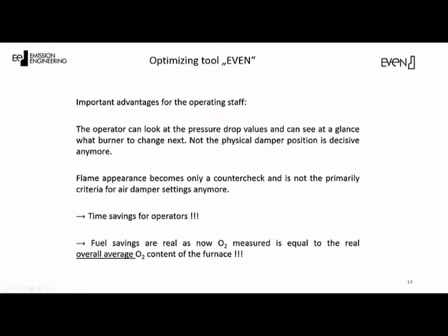Do you think this method is too time-consuming and complicated to understand? We assure you it's not. The measuring systems that we have in continuous operation are widely accepted, and in relation to the time effort, it is actually the opposite. In earlier days, it was very time-consuming to search for one or more burners operating too close to stoichiometric conditions and therefore producing carbon monoxide.